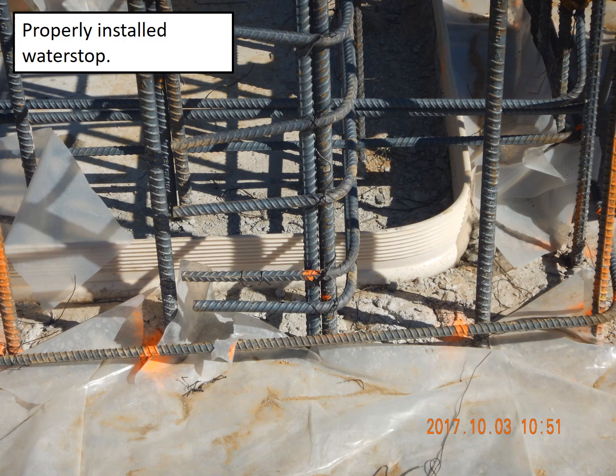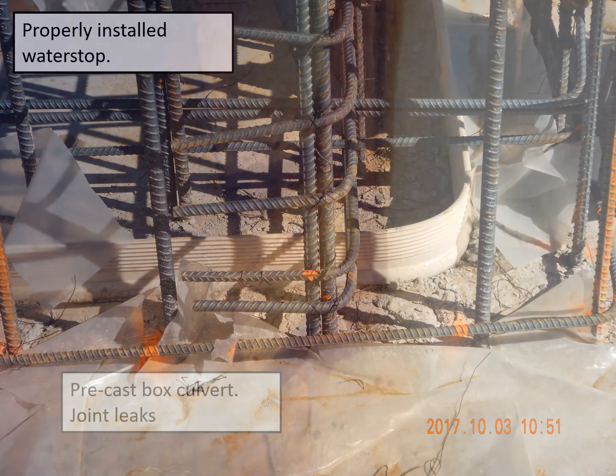At that bend, as opposed to it being cut and spliced and butt welded together, it's got this sweeping radius curve, which is a good detail, because anytime you have to splice and weld together water stops, you've got a potential location for a defect. So if you can just put this curve in there, that's all the much better. I have heard from some folks that there's one or two issues with this detailing overall, but we won't go into that. This isn't perfect, but it's pretty darn good.